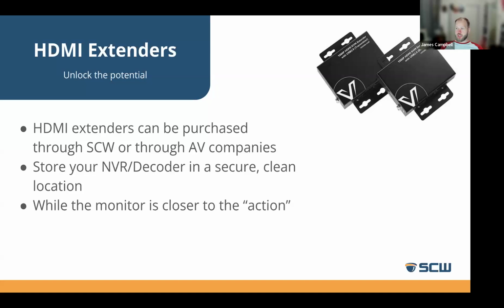And another advantage of this too is that, we're going to hit on the hazardous environment element of this, but a lot of these locations have a lot of things flying in the air, whether that's dust or metal slivers and everything like that. And so if the NVR is near the production line where the monitor is, that tends to suck in dust through the fans and everything like that.